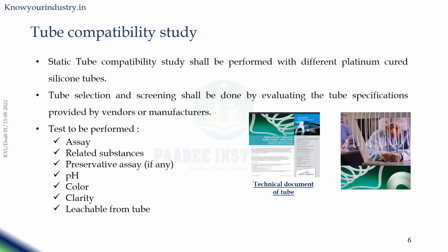perform the study. So similarly, in this case also you can do a hold time study with your tubing with predetermined time points and collect the samples and test based on your critical quality attributes. And also it is highly recommended to perform a leachable test for the transfer tubing also.